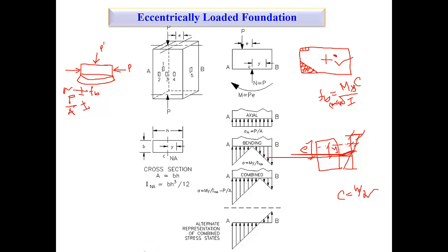Here, Y is the distance from the reinforcement to the neutral axis? No. From which fiber do you want to calculate the stress? Maybe here, maybe here. Which fiber you want to calculate the stress at, that fiber.